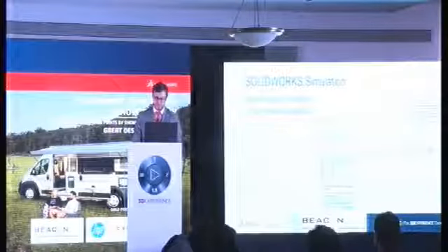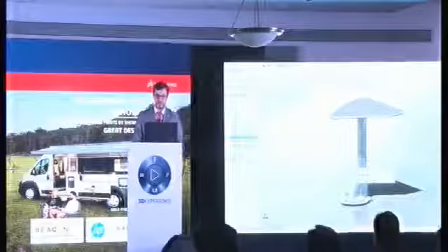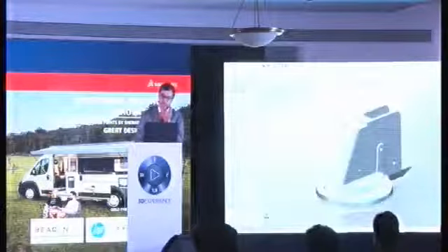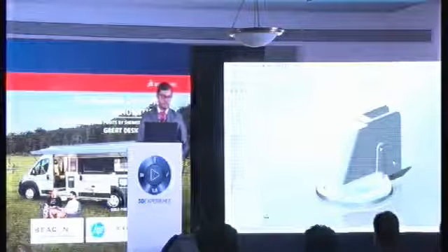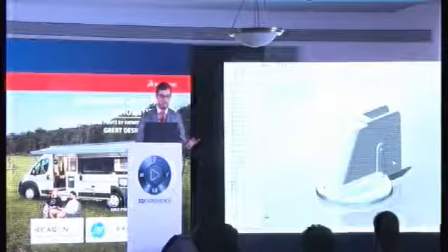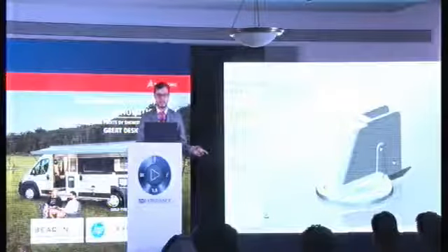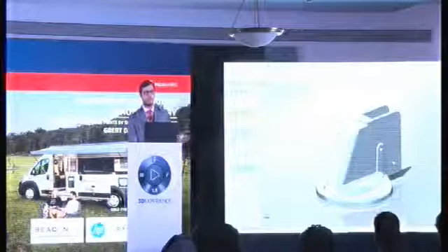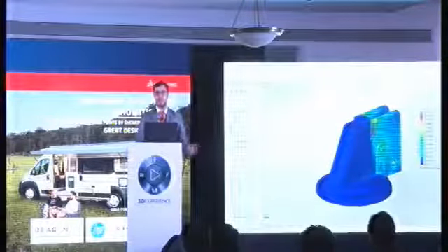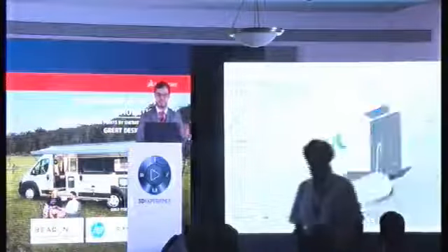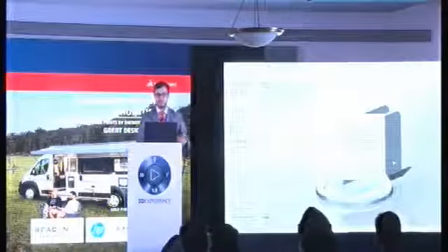So let's quickly have a look at how we can do this. Now I have this TV antenna assembly over here. I'll just select this component and open it. This antenna arm bracket. So I have a study over here. I can go to the hotspot diagnostic. So hotspot diagnostic will show you the areas where the stress is high. In 2018, you can go ahead one step and you can confirm the stress singularity directly inside the SolidWorks.